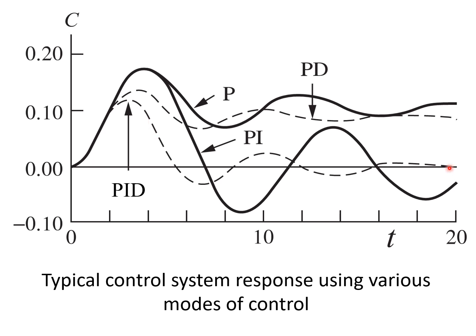So basically, we have a choice of what sort of controller we want to decide on for our system. Of course, we may want a PID controller, which looks like the best, but at the same time, we have a disadvantage: we have more tuning to do in PID. In PI, we have less tuning. So PI is good also, you get no offset, but there's more oscillation there. P has offset, but the tuning is easier. P and PD are easier; you don't have to tune too many parameters. And some offset may be desirable. So there is some decision to be made.